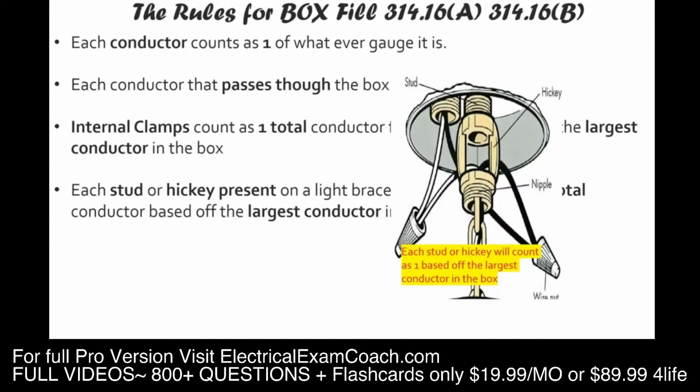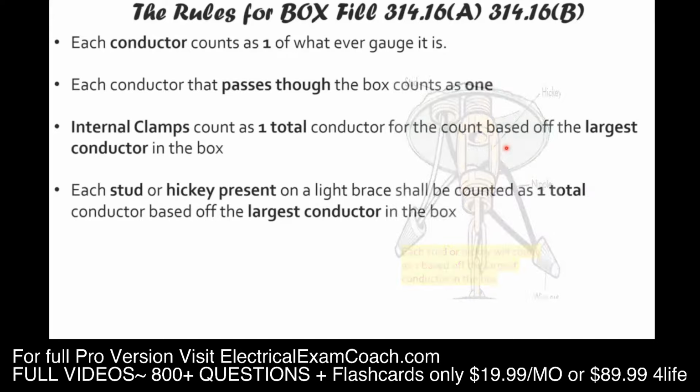Imagine that we're hanging a chandelier. This we would call the stud or the nipple. Or, this would be the nipple, this would be a nipple. But they're calling this the stud and this a hickey. And they still use this terminology on exams today, so you definitely need to understand. In this scenario here, in this picture, the stud would count as 1 of whatever gauge was in the box that was the largest, and the hickey would count as 1 of whatever gauge was in the box that is the largest. And we're going to do lots of practice, so don't worry about it.